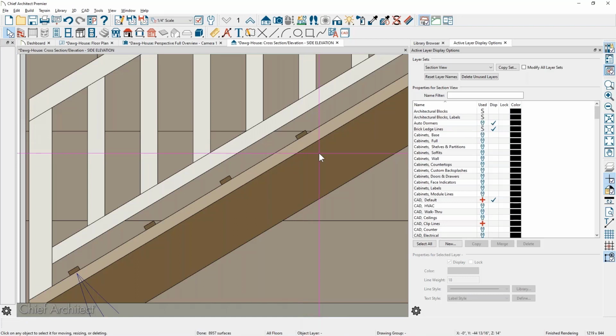Then use that multiple copy. And it's just kind of a quick way to position something. And that control key will override bumping and snapping for pretty much every object in the program. If you needed to slide a cabinet around through a wall, you could just hold your control key. It will override that bumping condition against a wall. So kind of a handy tool at times.